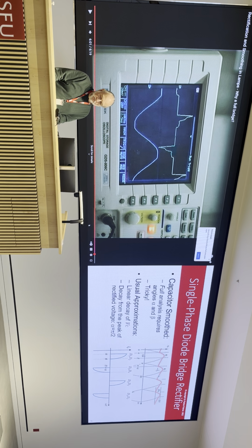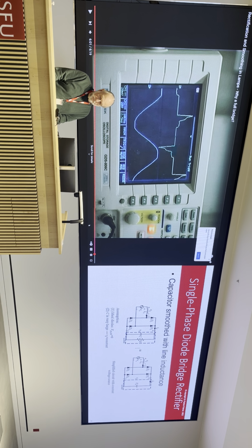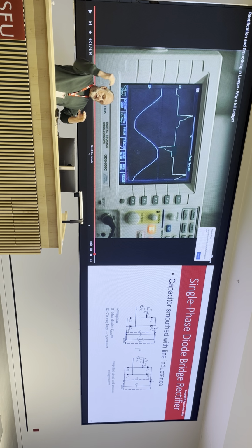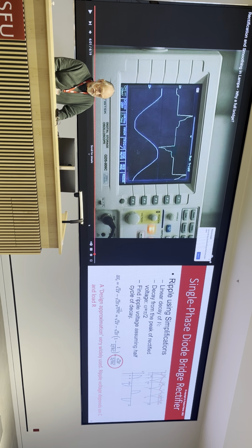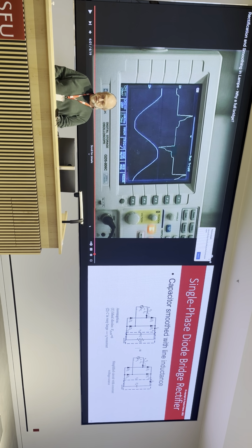The next thing to think about is, I've talked about an integrated circuit. We talked about that. That's fine. How about I put in a bit of line inductance? Because the line inductance will drop the volts and stop that big spike of current. That could be quite a nice thing to do, and that is often done on three-phase rectifiers. It may be done on a very big capacitor smooth job here. It's quite nasty to analyse because you've now got that inductor impedance to think about.